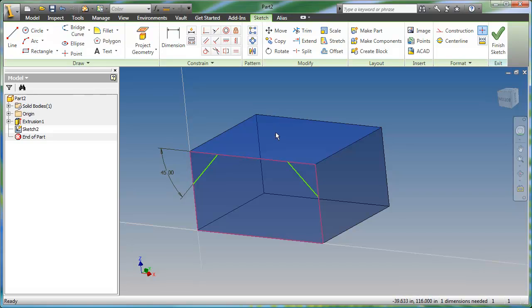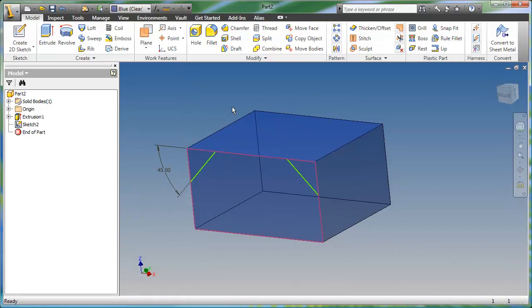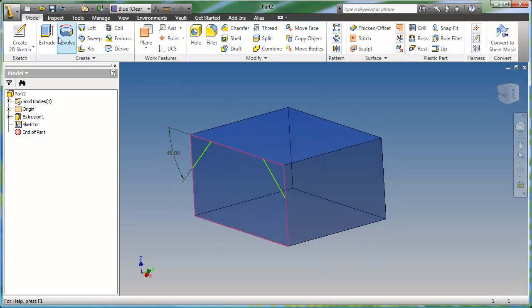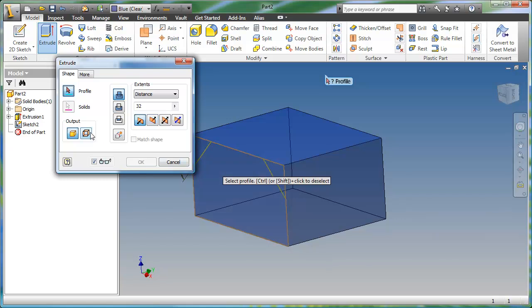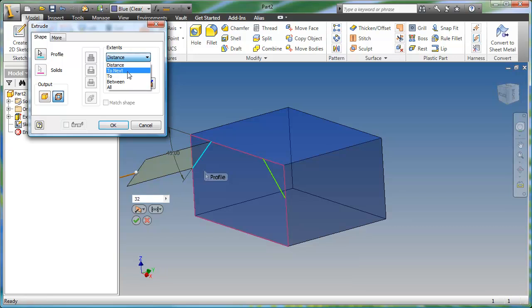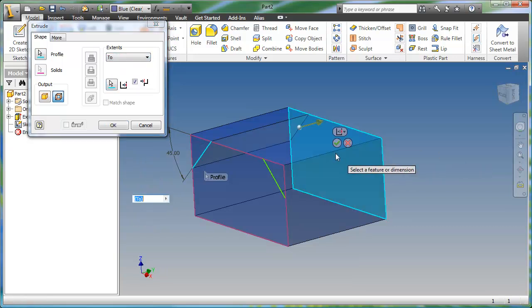Now I want them also on the other side of this little table. And you'll just have to bear with me till I get to the frame generator part. Then you'll be able to actually visualize this. I'm going to go ahead and extrude this. I'm going to extrude this as a surface. And I'm going to say 2 and pick on that face and just add that surface.